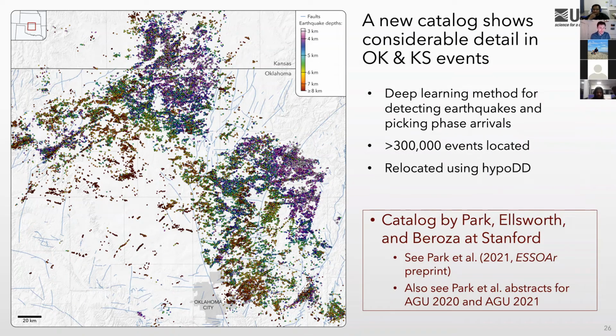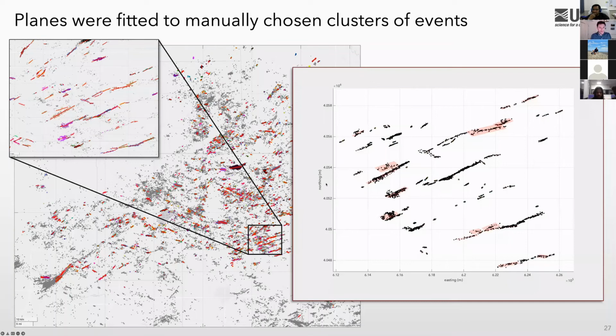And so here, I've been manually identifying faults across this area by selecting individual groups and then fitting planes to them using eigendecomposition. And so this is the northern group. There's about 1,500 faults so far. And I just want to show you a subset of those. This is all map view, and you can see a lot of strike slip faults in this area, just as we would expect from the state of stress.